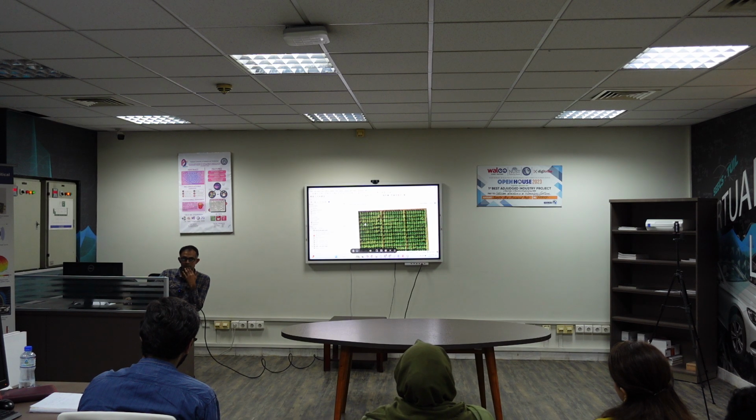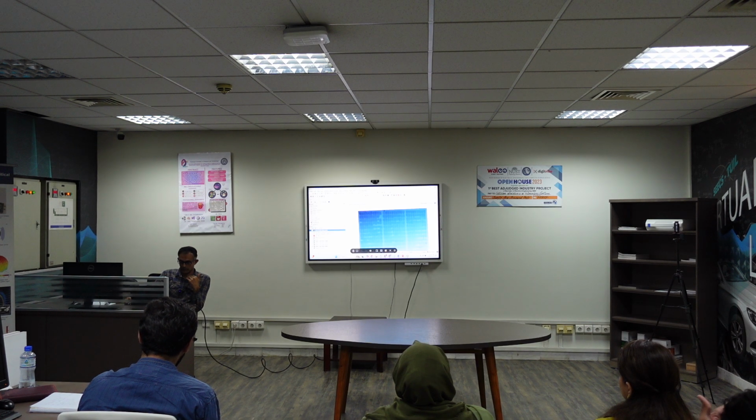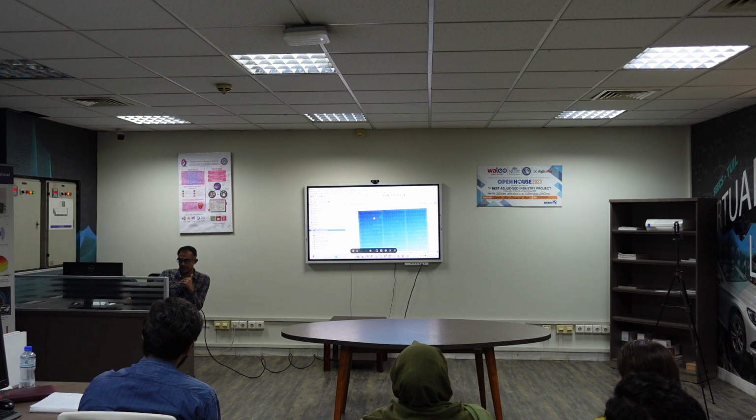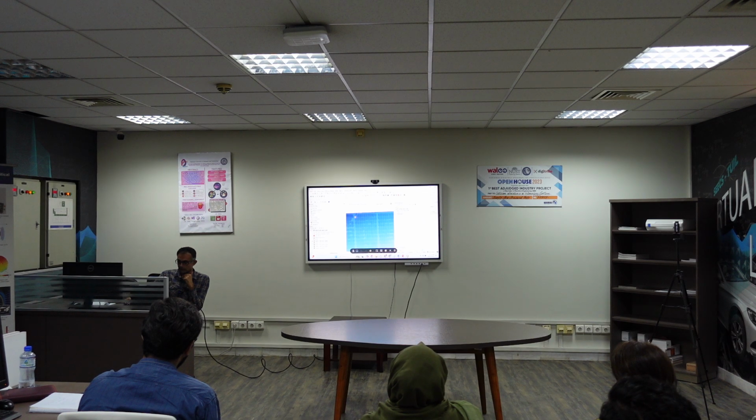There are plenty of options, like you can use radar, which gives a much more accurate height parameter. However, we have used simple imagery using structure from motion. We derived this digital surface model and came up with a height model of that plot. What we got from that photogrammetry processing is this map. This holds the information for each plot like this.